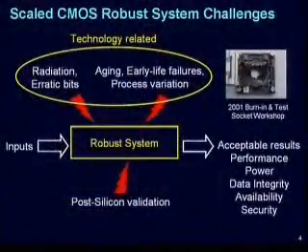Now if you test these chips too much, for example, if you stress them too much, this is what happens to the chips. And this was actually one of the highest performance microprocessor chips from a company, not Intel, because I used to work at Intel. You can see that because of extremely high leakage currents in the burn-in oven at a higher temperature, these chips actually were fried.